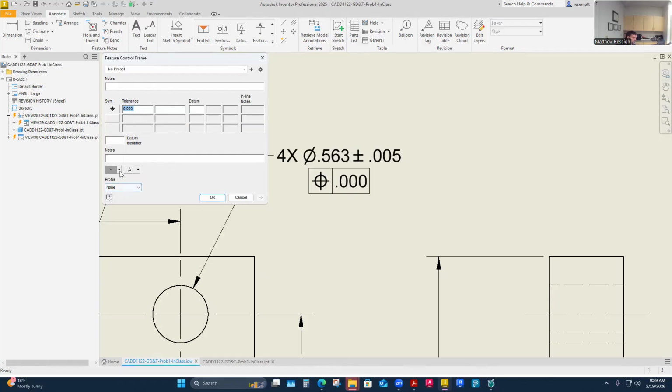And then I can add, here's a little symbol library, I think, to insert just some standard symbols: diameter and degree here, plus or minus. I want the diameter sign because my tolerance zone is a rounded shape. The whole concept of moving from rectangular tolerance zones in this situation would be that I want a round tolerance zone.